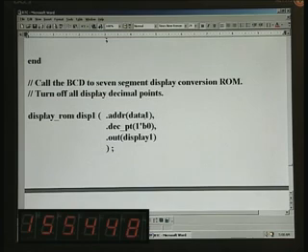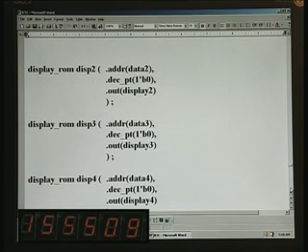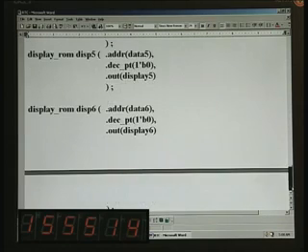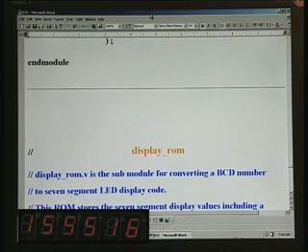There is an address input which can be given as data 1, data 2 and so on, so that we can straight away do the code conversion from BCD to 7 segment display, and that output can go to, say, display 1. If you want to independently control the decimal point, you can put 1 here. So precisely like this, display 1 through display 6 we have here, and each time different data, data 1, data 2, are sent here, and that is the reason why we get a display, and that ends the design.